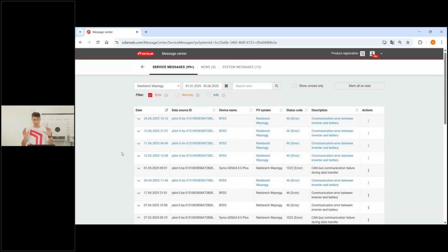So in total, if a service message or an error message appears, if the light flashes red, no panic, check the service message in Solar.web, follow the suggestions, and if that doesn't work either, then contact the PV installer. That's the message you should give to the PV owner.